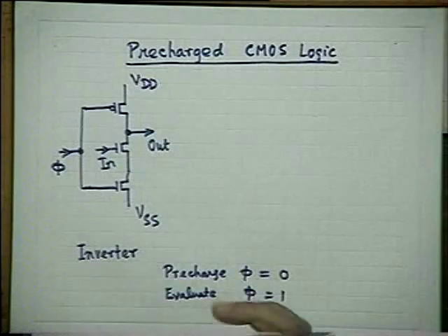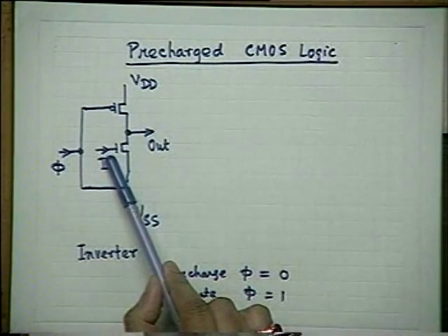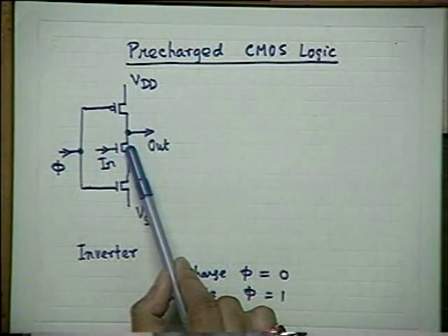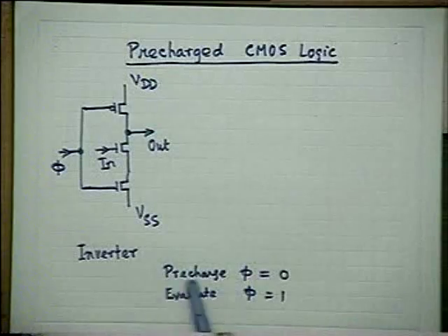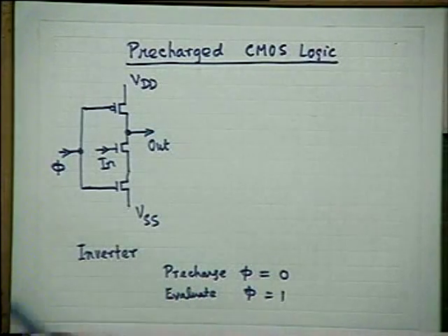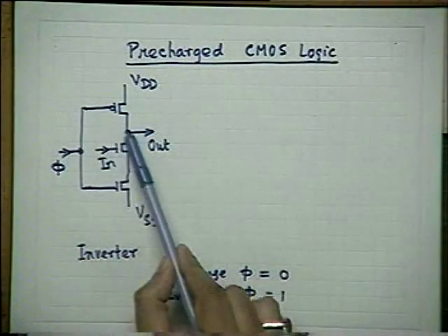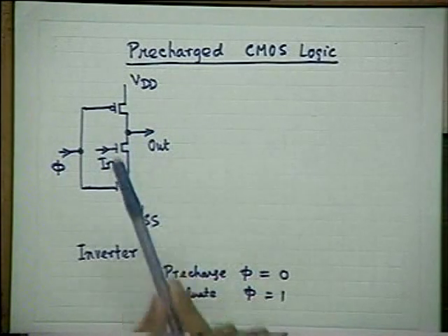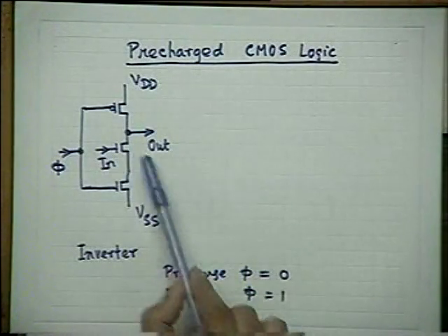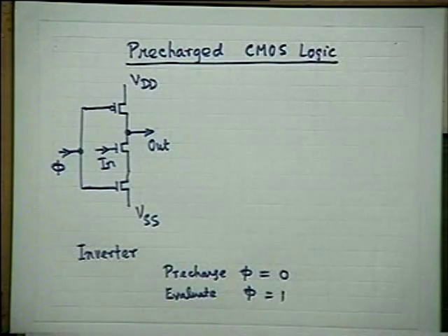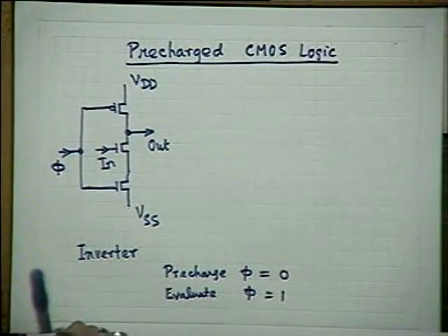There could be a block of transistors in this place, with different signals at the inputs. During this precharge phase, you have allowed sufficient time to settle this block to certain on-off states. All the transistors in this block, here I have shown only one transistor because it is a simple inverter.